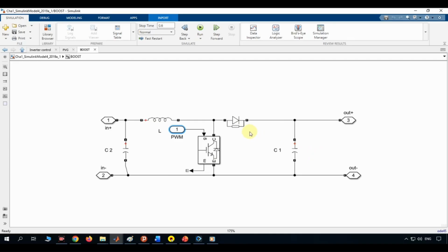There's also a diode drawn inside the same symbol, in parallel with the switch. This is a built-in freewheeling diode, and it protects the switch by giving any unexpected reverse current a safe path to flow, rather than damaging the switch itself.